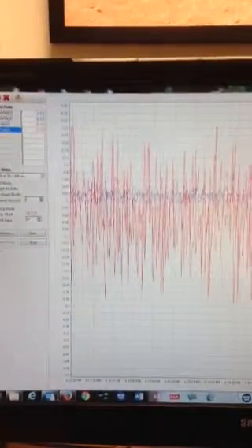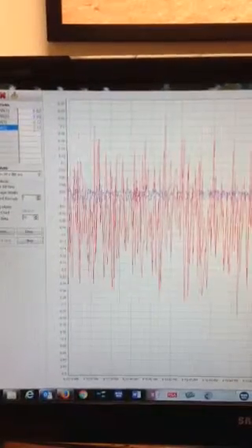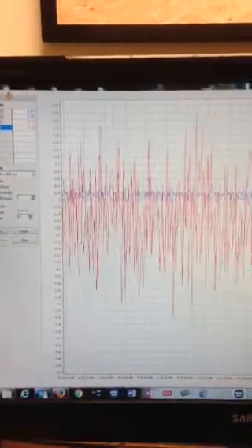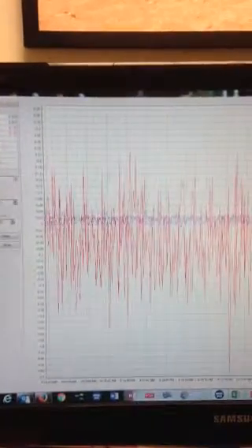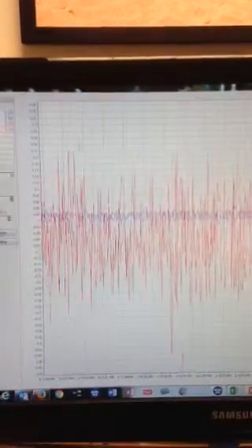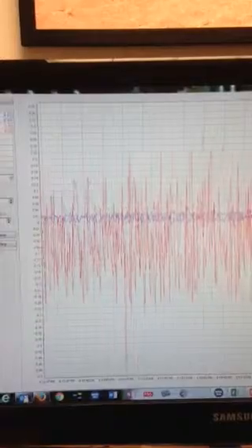We're going to go ahead and calibrate again to just bring everything back to 0. Neither of these gauge sets are temperature compensated, and the temperature in this room is varying quite a bit, so they do have a tendency to drift.